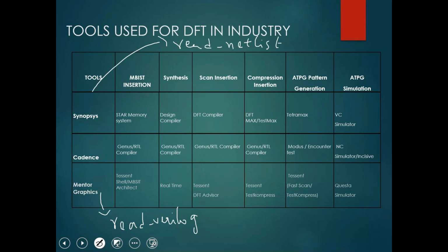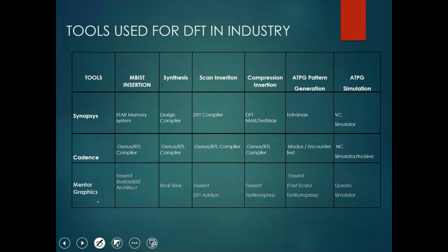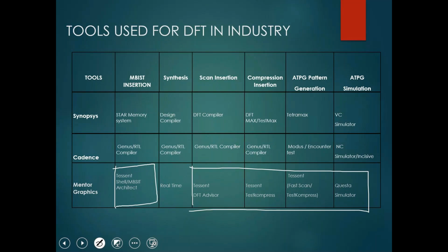So in the institute also, for your current batch, we are going to use the Mentor Graphics tools. And I'm going to explain about the synthesis also, because it is interlinked with some part of DFT. I will not go into the functionality of the synthesis, but I'll explain it. We'll use the tool called Design Compiler, provided by the vendor Synopsys, for the synthesis that converts the behavioral Verilog code into the gate level structural Verilog code. So we are going to see that.